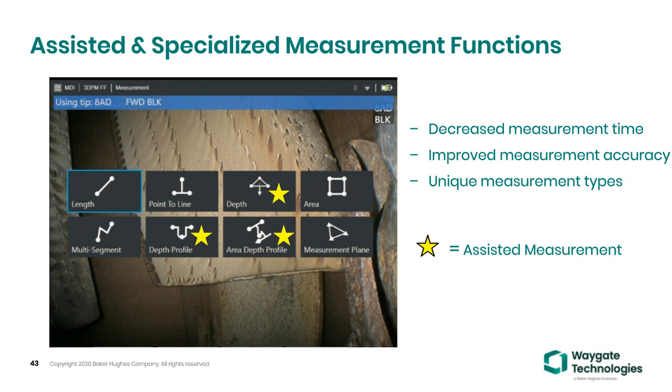For the traditional depth measurement, after you create a reference plane by creating 3 cursors, the MVIQ will automatically place the 4th cursor at a point which is either at a maximum height or minimum depth from the established plane you created with those 3 cursors, in the vicinity of those 3 cursors.